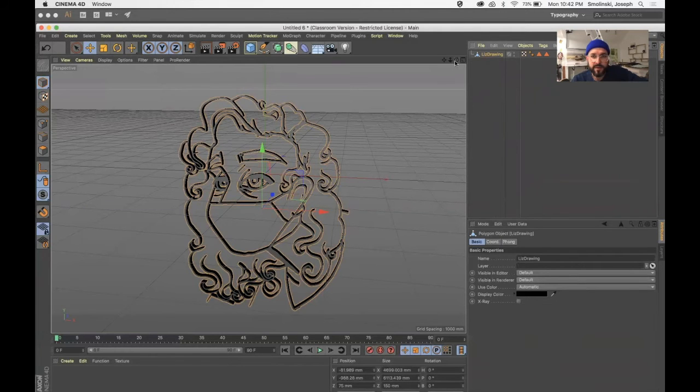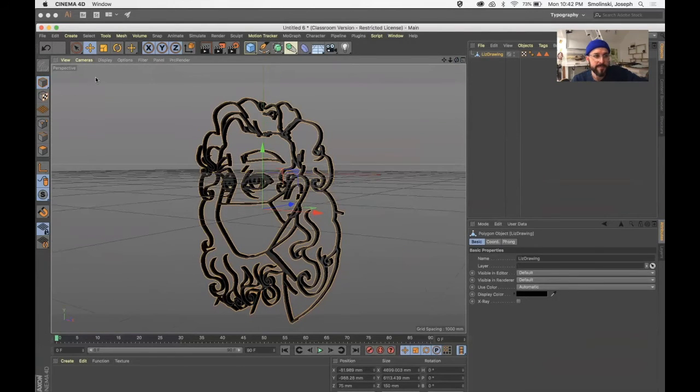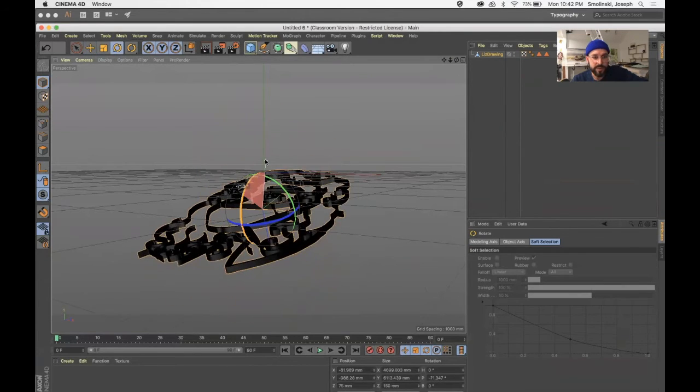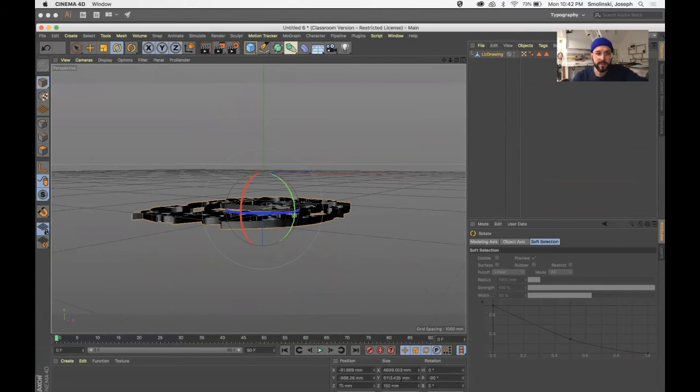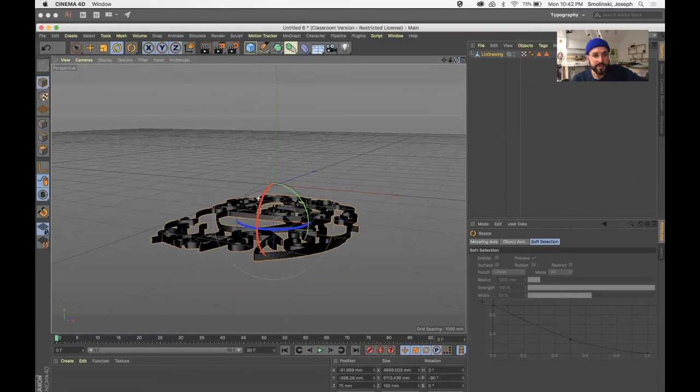So I would take this now if I wanted to 3D print this. I mean, I can't print it like this. What I would do is rotate this. So I would go to the rotate tool and put it down on the back like that. So down here I'm going to do -90. All right. And then what I like to do is rotate the axis. So if you click on this enable axis button, I can go back down here and rotate this to 0. There we go. Okay. And now if we notice that the Y is going up again, so that's good.